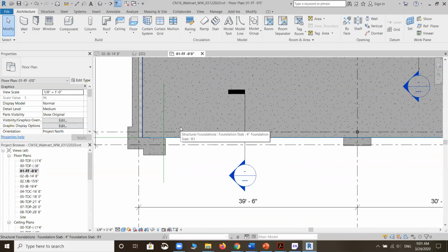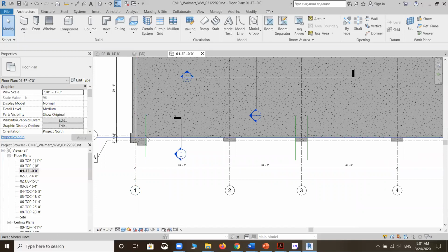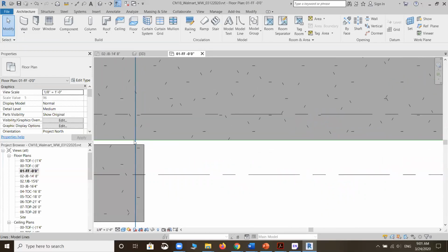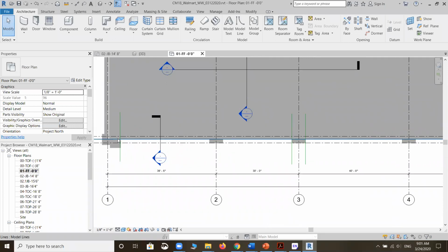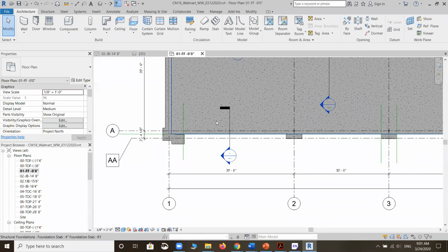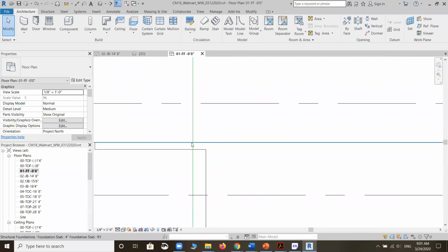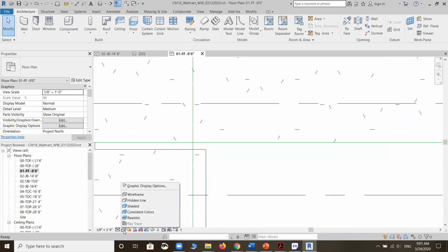So we know that the first section of curtain wall is going to start from this intersection of the reference line to this intersection of this reference line, okay? Again, sometimes you find those colors quite annoying. You can actually turn that off by going to hidden line. It's easier to look at, so that intersection would be a little bit more obvious. Again, it's here, the view style, you change that to a hidden line.